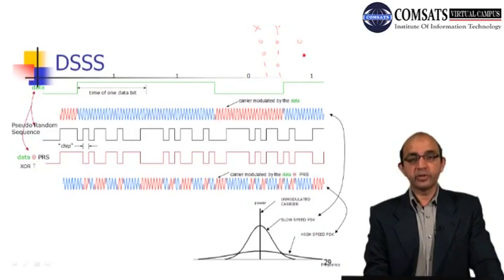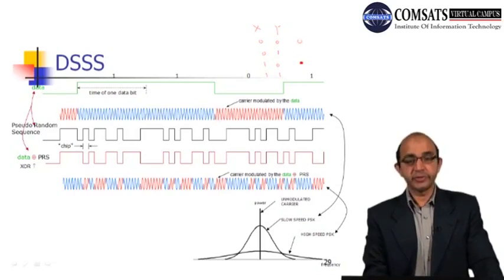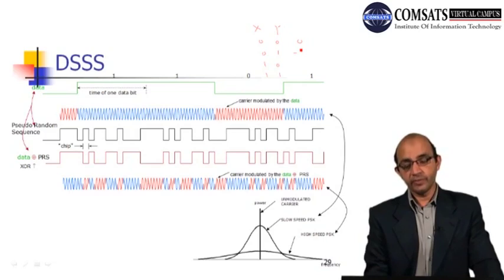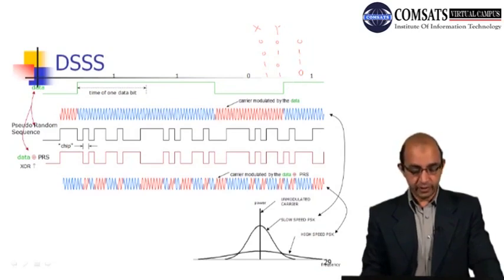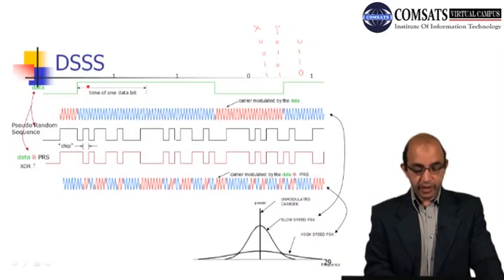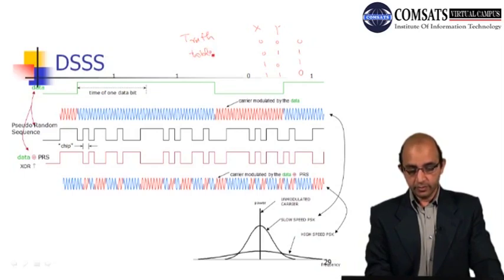When both inputs are the same, XOR produces 0. If any one of the inputs, either X or Y, is 1, then we have a 1, and again when the two inputs are the same, we have a 0, right? So we can look at the implemented truth table. Let me write down, this is the truth table for XOR.